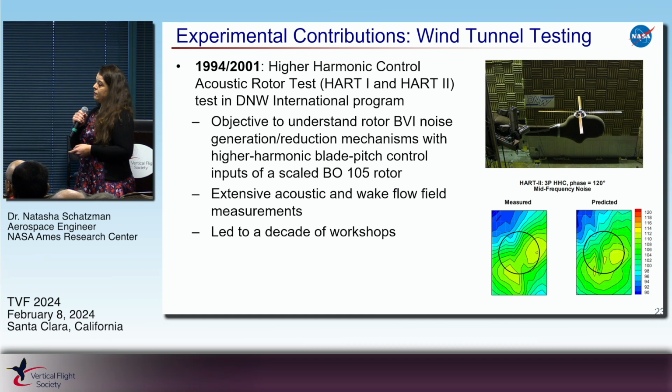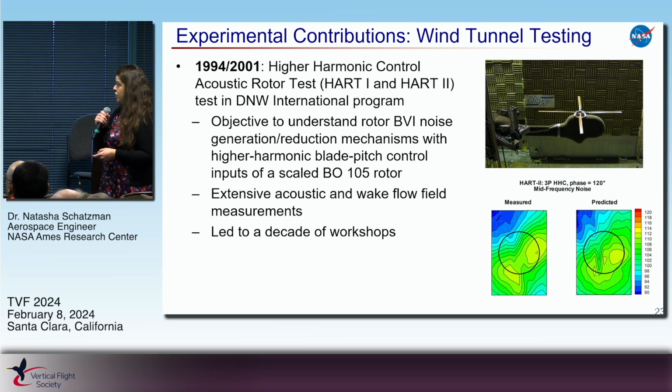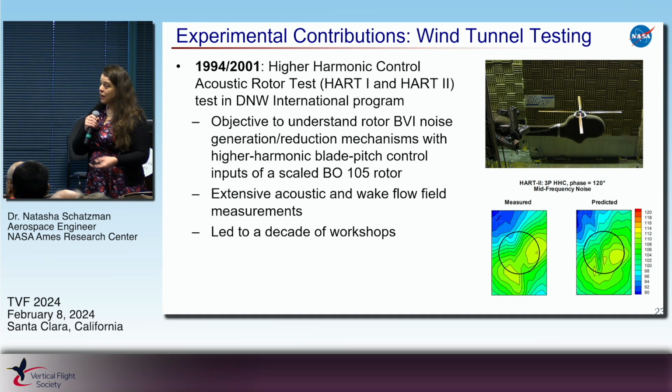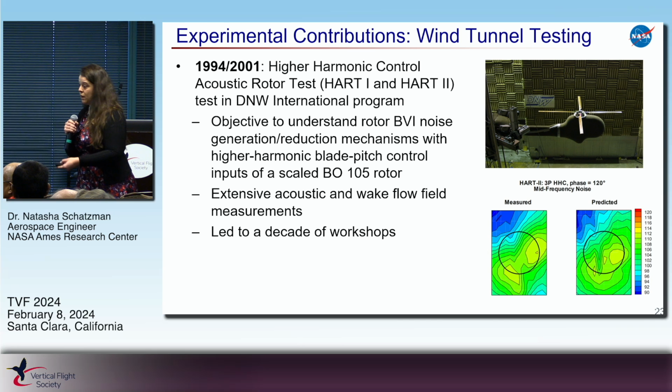The objective of this test was to understand BVI noise generation and reduction using higher harmonic blade pitch control of a scaled BO-105 rotor. For this test, they took extensive acoustic measurements, of course, and also wake flow field measurements. Again, this led to a decade of workshops. All that effort was not lost; all that data led to further improving our codes and learning more.